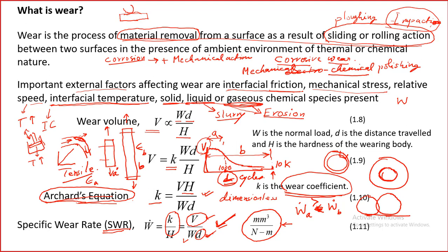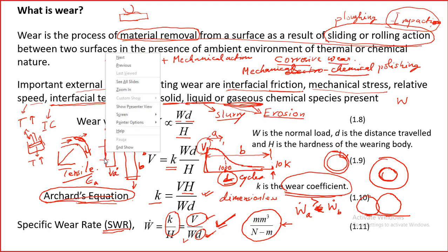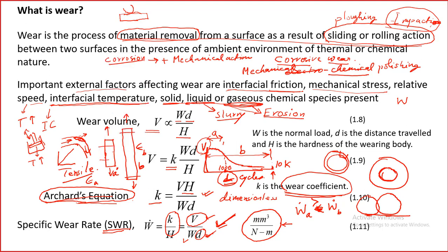In general, when we deform the material, we assume that there will be a uniform deformation, right? Initially elastic and then plastic deformation. But in reality, it is not uniform. What happens in, let's say, mild steel? What will happen once it crosses the elastic limit? Then it gets into the plastic range with permanent deformation. Yeah, but the problem happens because of necking. Have you heard about necking? Yes, sir. The cross-section area decreases a lot.